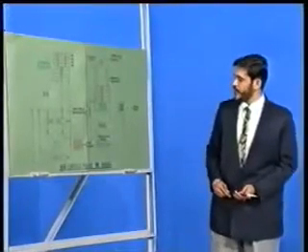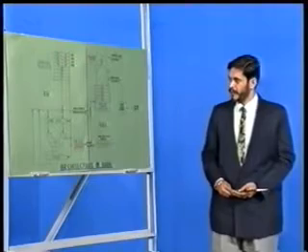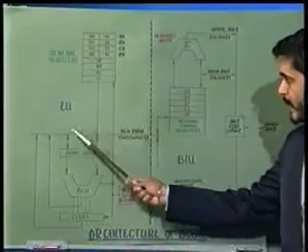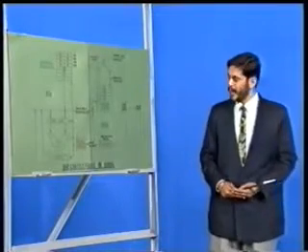The bus interface unit has the main function of fetching the instructions from the memory, while the execution unit simultaneously decodes and executes those instructions, thereby providing parallel processing.